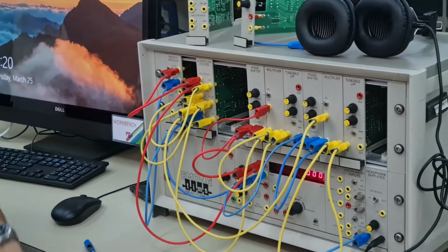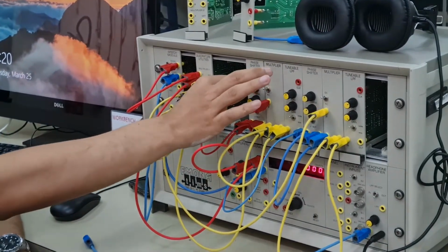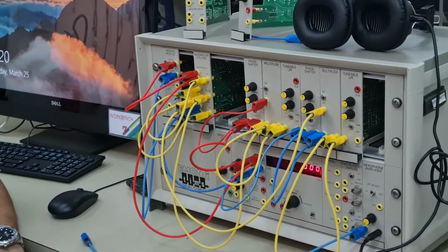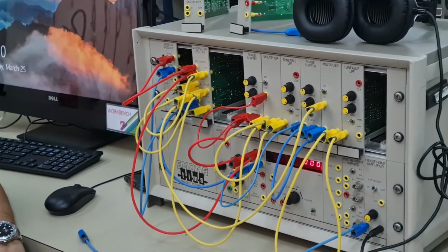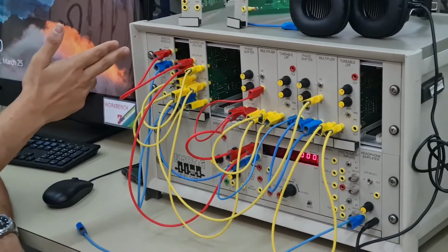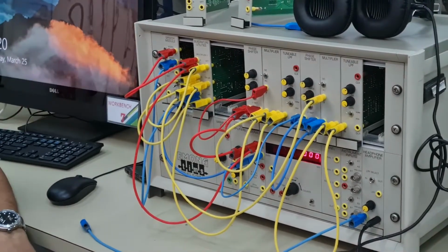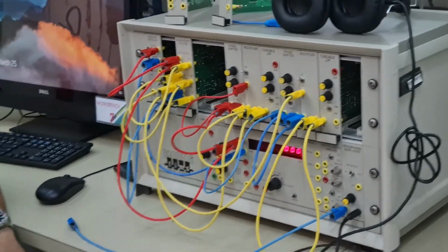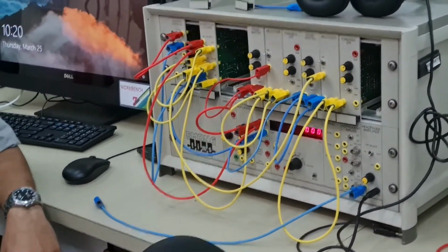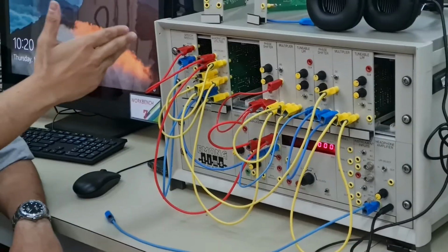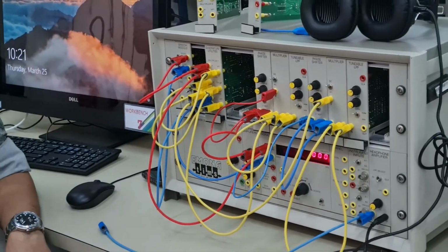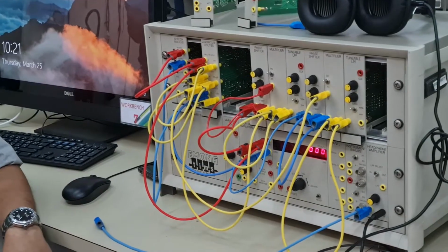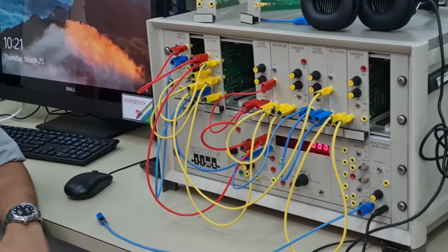How do we tune the phase shifter? We just tune it, keep changing it until we get the correct signal. How can I confirm? We know our signal, so we wait for the same signal. But in reality, we use different kinds of techniques to find out the phase of the actual carrier, and then automatically tune it. So this is a control feedback. You keep doing it until the error is 0.